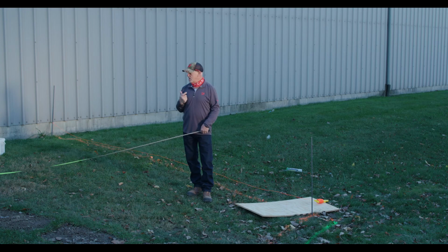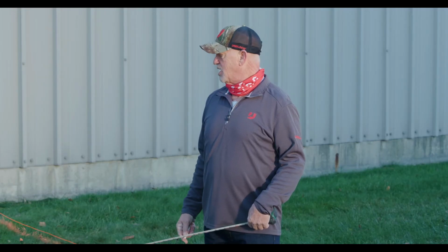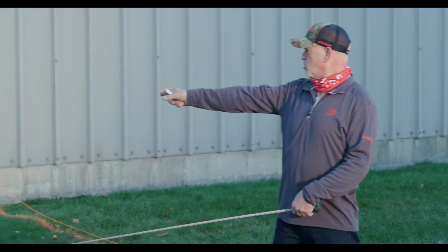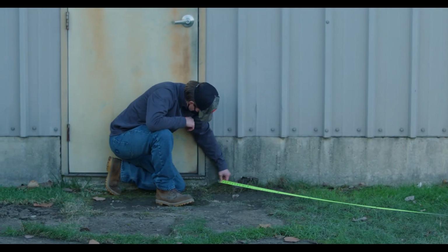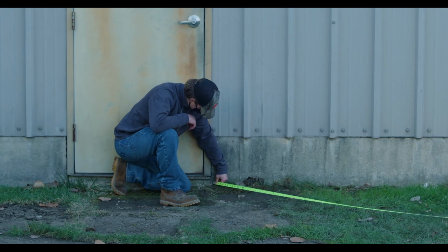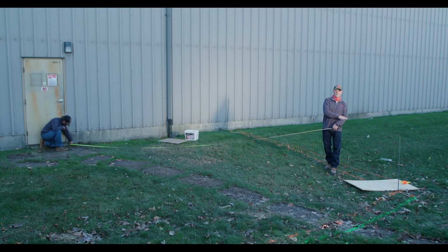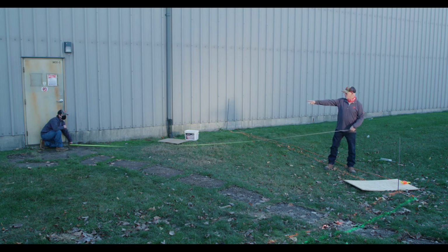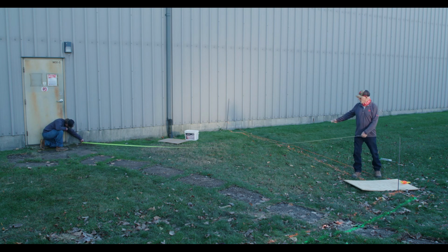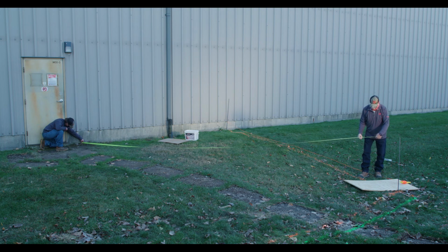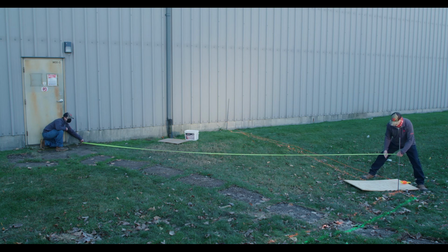So with that being said, I like this methodology here. Jim, you're going to hold 1 foot in again to that mark at 15. All right, we're going to reestablish that 3-4-5 rule here, but I'm just using some heavier medium to be able to accurately mark that. So here we'll use the pencil on that. Jim's going to hold me 1 foot over to 15-foot mark. All right. I'm going to remark our 25-foot curve.